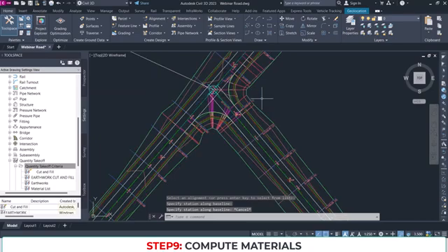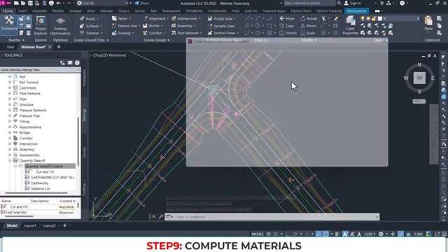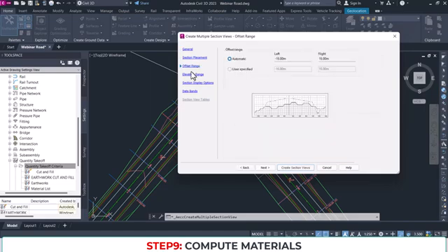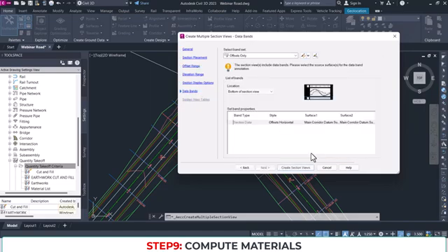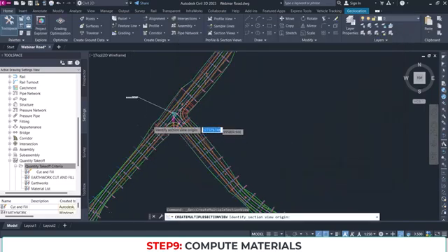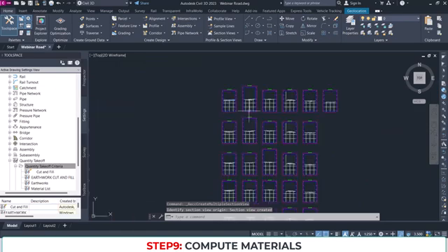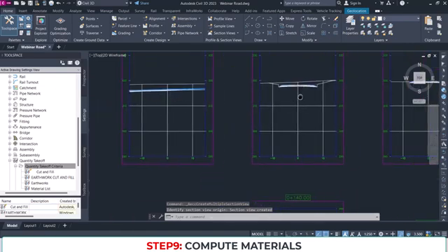So we now go to create the section view, creating multiple views for it as well. We are going to use road 2 this time, and then sample line group 3. That's the name automatically given for the sample lines associated with road 2. Every other thing I'm going to leave by default. Let me create the section view. I'll place it to the right-hand side of this. Again I can choose how this changes.